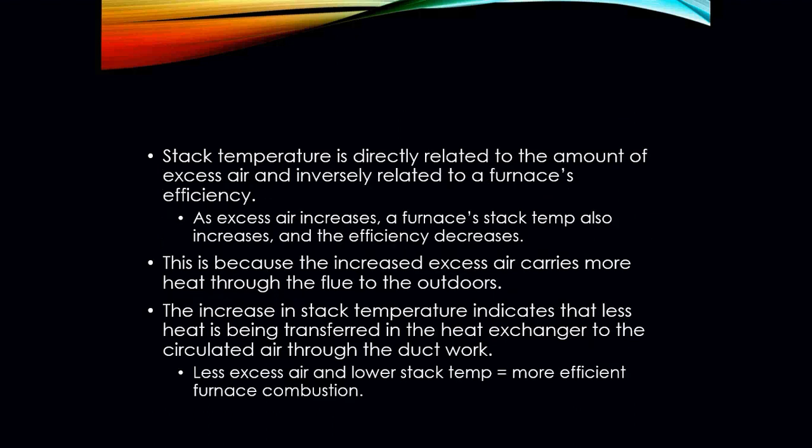Stack temperature is directly related to the amount of excess air and inversely related to the furnace's efficiency. As excess air increases, a furnace's stack temp also increases, and the efficiency will decrease. This is because the increased excess air carries more heat through the flue to the outdoors.